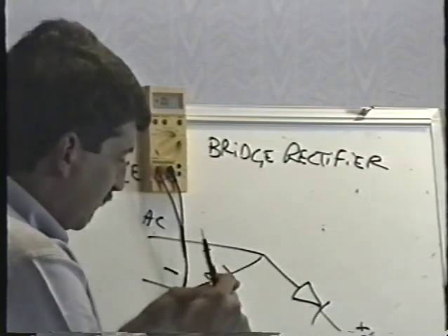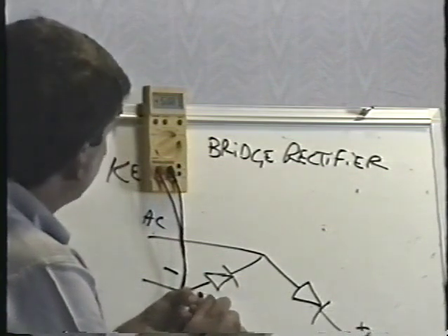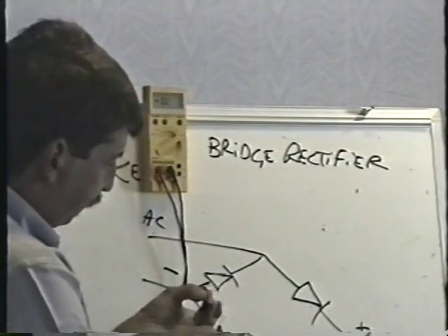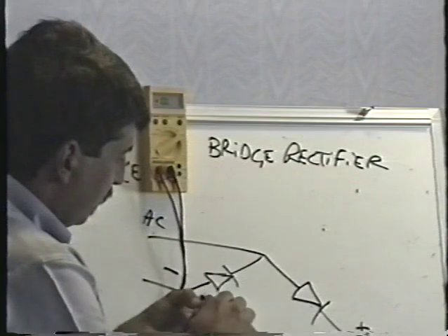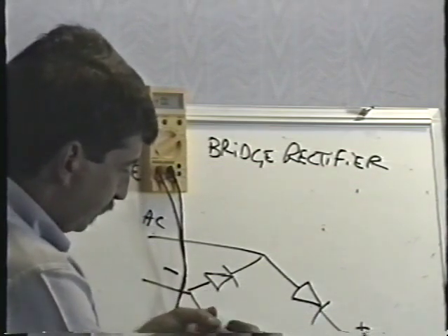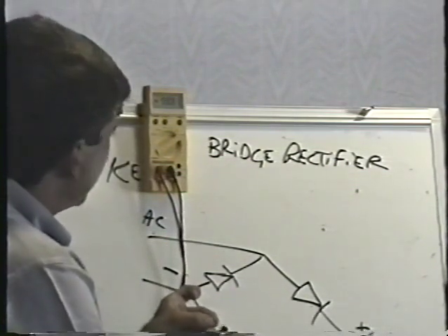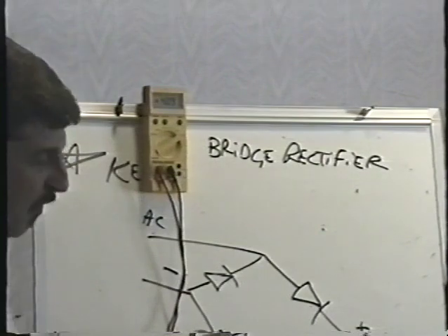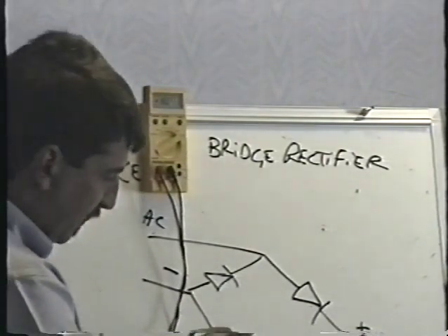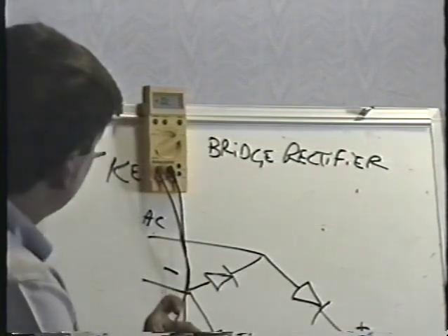Maybe this diode's worse than I thought. Junction, 0.54. Reverse your leads, open. That diode's good. See, this one's really giving me some weird readings. Now I got 0.4 on that one. That's really strange. That's pretty darn low. I get an open the other direction.